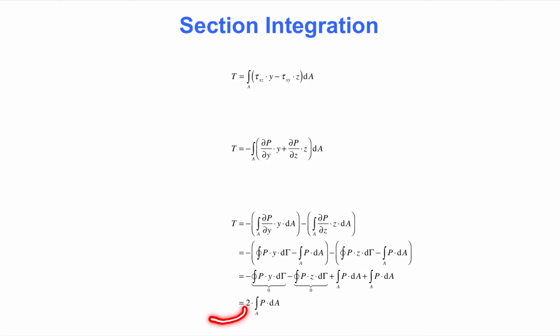For certain cross-sections, such as the open thin-walled cross-sections, equilibrium of the shear flow appears to give a torque that is half of this value. To address this puzzle, it is first noted that the integrand of the integrals on this slide consists of two contributions from shear stress in perpendicular directions. For certain simplified stress functions, such as the one used for thin-walled open cross-sections, which is the half-cylinder shown on the previous slide, the stress at the short ends is neglected, which causes the apparent anomaly. In actuality, there are shear stresses at those locations.